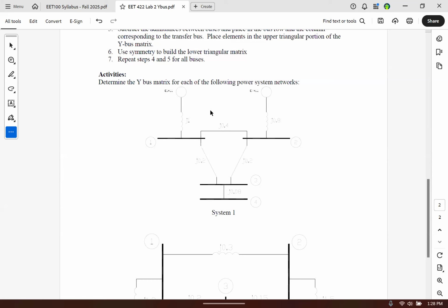It's almost like the system is unloaded. It is powered, but you get 1.1 at an angle of 0. It's an unloaded system, right? How much load is on the system? You don't see anything going. You see connections between the buses, but the voltage sources all have the same magnitude and angle, so they're not going to act as a load to each other. Is there any load going out onto the system? No, all these buses are just energized. There's nothing sneaky going on, so it's an unloaded system. So they all should be 1.1 at an angle of 0. It should be that case.